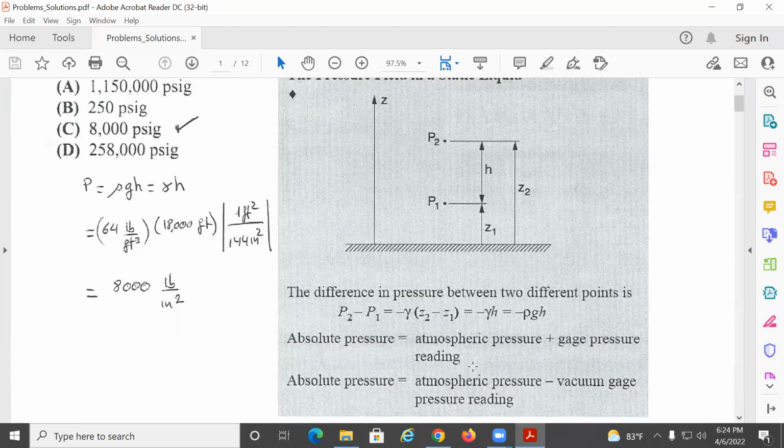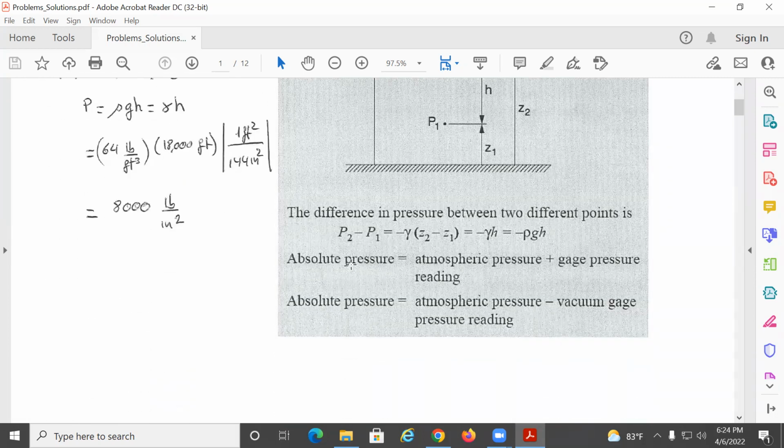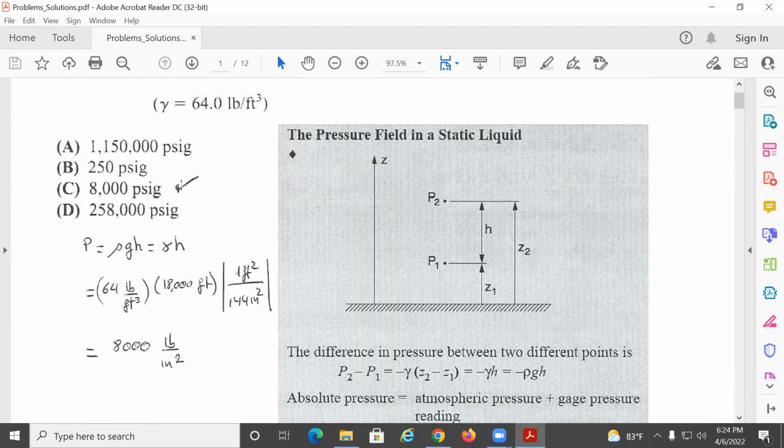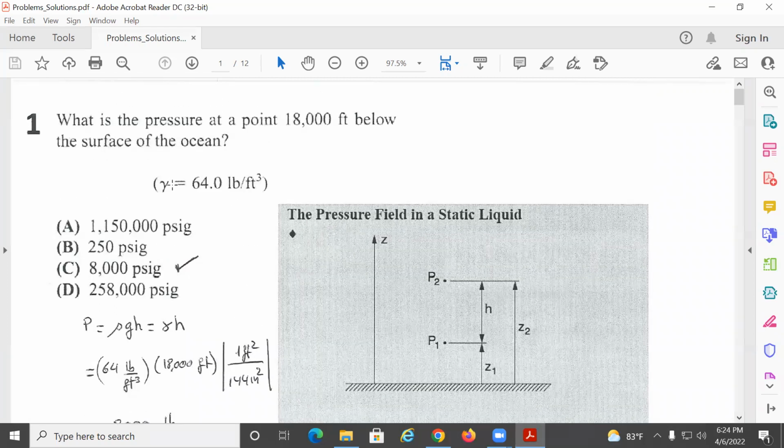And here you also have some type of responses. Okay, all these problems correspond to the problems I gave you. So you see on the problem statement, they give you the equation. And you need to pay attention here to the units because the trick is to realize that they ask you this in PSI, which is pounds per square inch, and they give you the data in square feet. So you need to do the unit transformation. Here they give you the gamma, which is gamma h, okay?